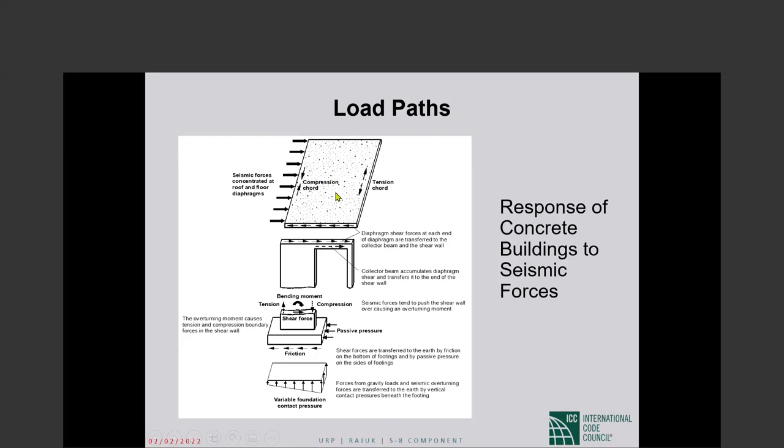This is a slab on the roof which, under lateral loads due to wind or earthquakes, bends in its own plane like a deep beam. So when it bends under lateral loads like this, there is compression along this edge, tension along that edge, and shear along edges parallel to the loads.